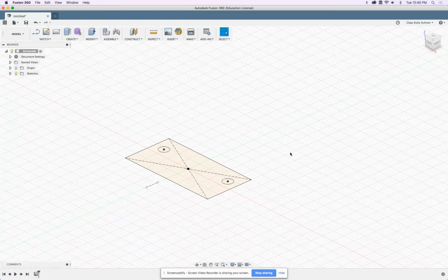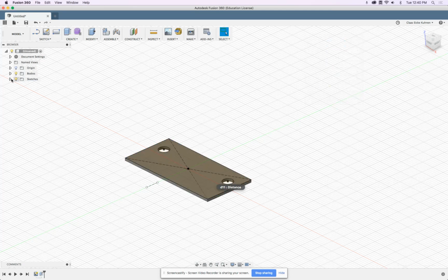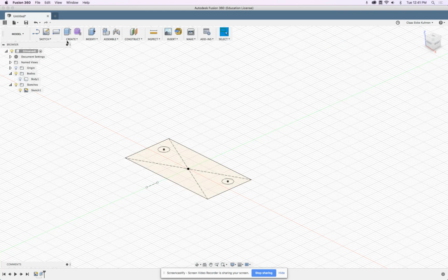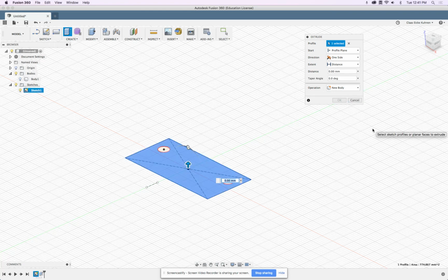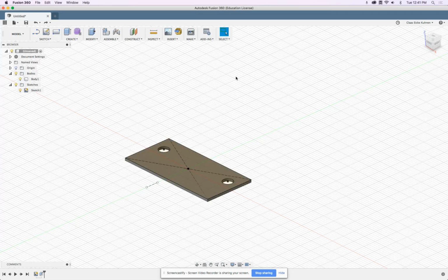Okay, so there is a small spacer 1 millimeter below. So I can click this 1 millimeter, minus, scroll down. Very good. Say height. And I could now add 2 millimeters on top. And then on this face, I would have to create the next sketch, which is something I could do, but I don't really want to do it. So I will undo my step till the first one.